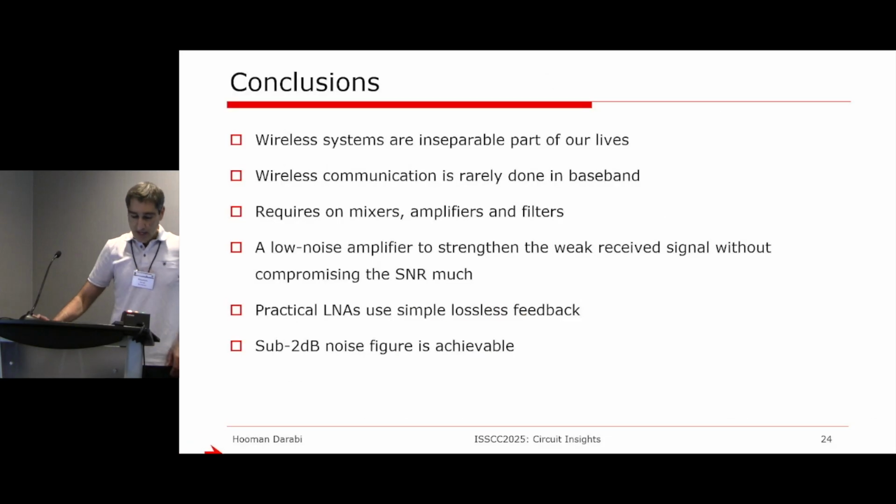And to conclusion, I talked about wireless systems and circuits. They are inseparable parts of our lives. We can't live without them. Everything we do nowadays is thanks to them. They consist of mixers, amplifiers, and filters, and a whole lot of them. As a case study, I showed you a circuit of low noise amplifier, which oftentimes, and in this example that I showed you, is designed by incorporating lossless feedback, and you can achieve good sub 2 dB noise figure out of your circuit of LNA. So that's my talk. Thank you.